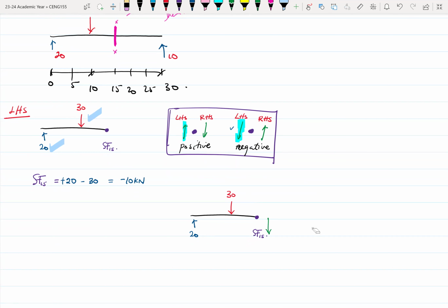Yes, there'll be the bending moment and the axial force and all of that, but if you are summing up vertical forces, only vertical forces get summed up. Normally when we are dealing with shear forces, we usually neglect the other unknowns because they don't really add up to the shear force. Shear force simply means vertical forces, at least with regards to beams.